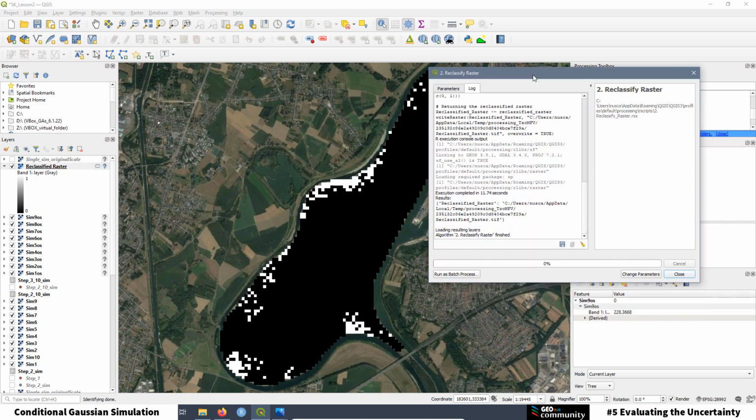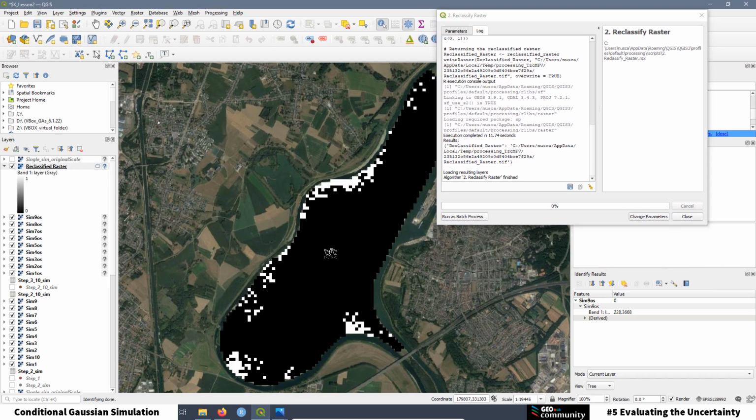Then again, if we take this tool over here and we select any pixel, you are going to see the values of the pixels. Here is 0, the white part. As you can see, now it's changing to 1. 0, black part, 1, white part. All the white pixels are indicating that the concentration of zinc is higher than 1000, and all the black pixels are indicating that the concentration is 1000 or below. 1000 for a zinc concentration is really high.